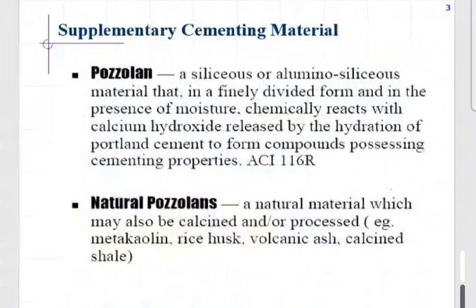So what is pozzolan? Pozzolan is a siliceous or aluminous material, which is finely ground. And once the cement comes in contact with moisture, it chemically reacts with the calcium hydroxide. If you go back, a while ago, 10 to 20 minutes before, we discussed that the major constituent in the cement that is causing the problem was insoluble calcium hydroxide. Student, if you remember,